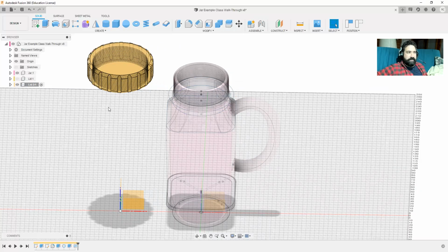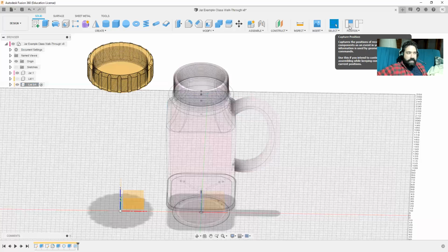Well, I moved something, and then when I made an adjustment, it kept snapping back. When I moved that and hit the OK, this new option came up. There's revert, which will snap it right back to where it was, or capture position. Pressing this button locks your moved object, your moved component, body, whatever you've just done. It locks it into those new coordinates within the build area.